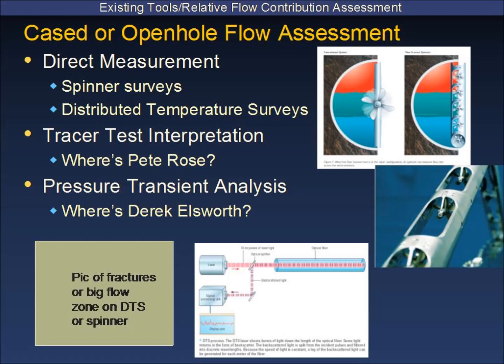Now, there are things that will enable you to consider flow contribution from various horizons in the wellbore, but of course the well has to be flowing for those tools to work. And so we have things like spinner surveys, and I've given Schlumberger a free piece of advertisement here with their flow scanner tool. But this is a really nice thing, because if you have 2 phases or multiple or even 3 phases flowing in the wellbore, this is the tool for you, because it has both electrical and optical sensors, and so you can distinguish gas from liquid and you can distinguish oil from water, assuming the brine has some kind of conductivity associated with it, and the oil does not in general, by looking at the resistivity measurements. So that sort of stuff works very, very well to identify where the flow is coming from in a well.